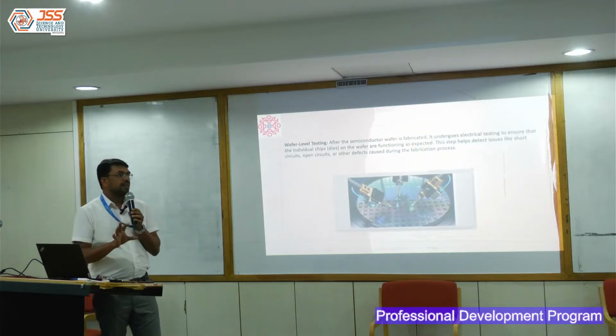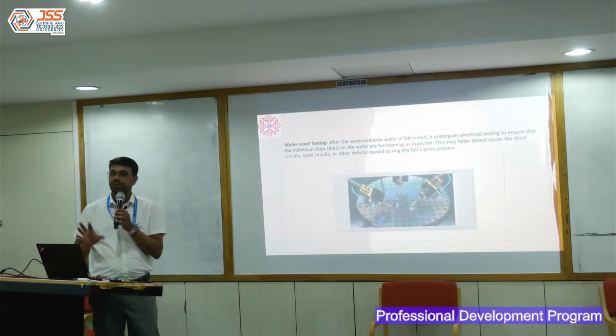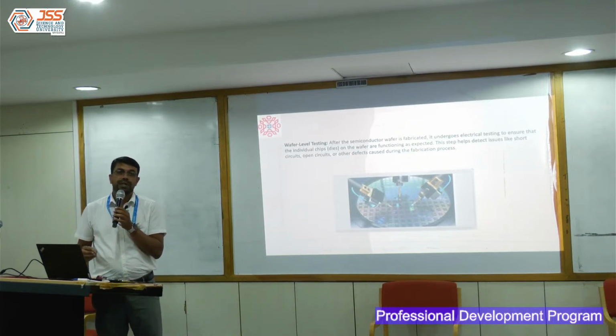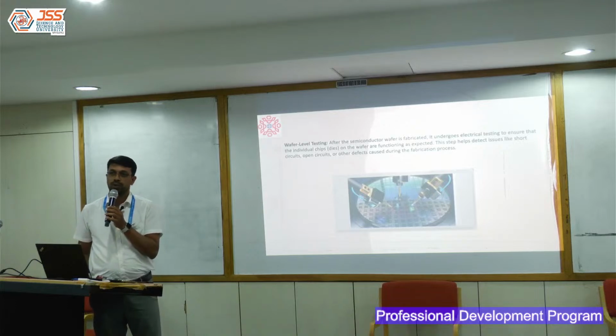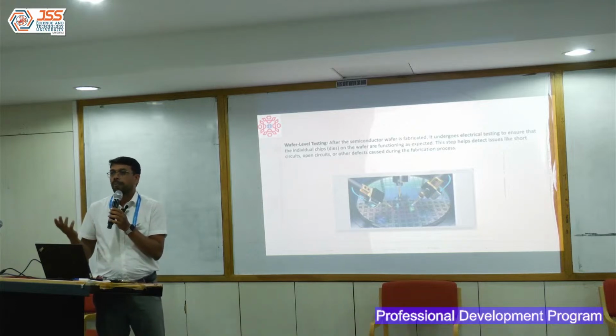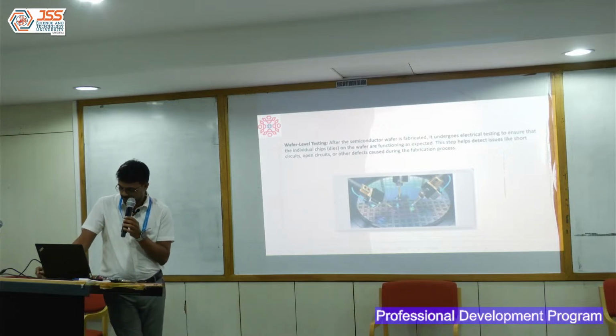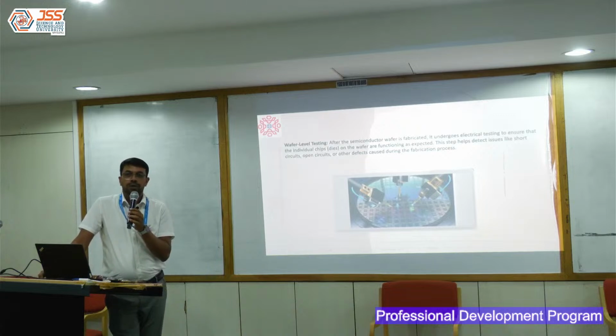So this is just a small introduction into the way testing works and the way we decide what is a good chip to ship, or how you meet the DPPM that is set by the customer. One thing which comes here is yield. Yield is like, say for example, on a wafer, if I can get 100 dies, if all the 100 dies are good, my yield is 100%.